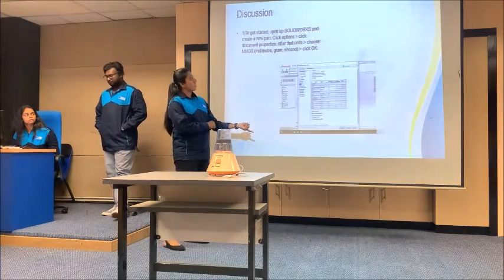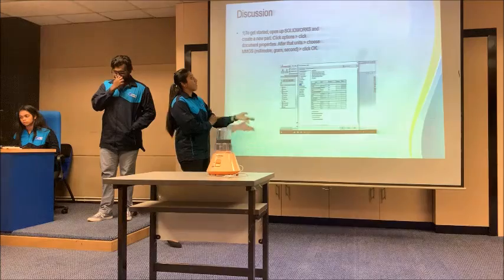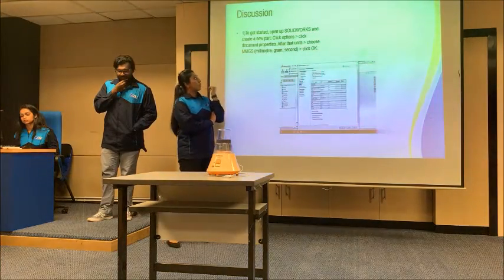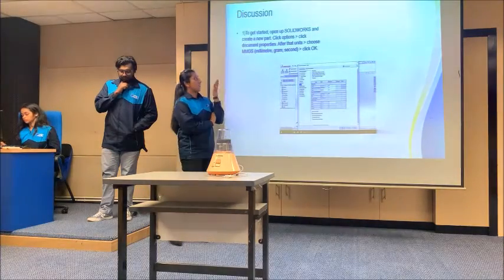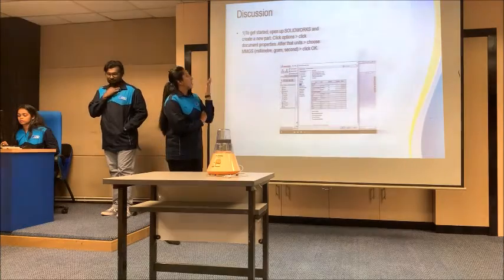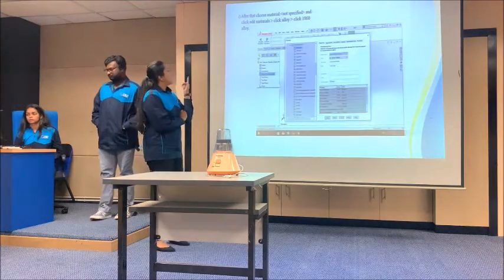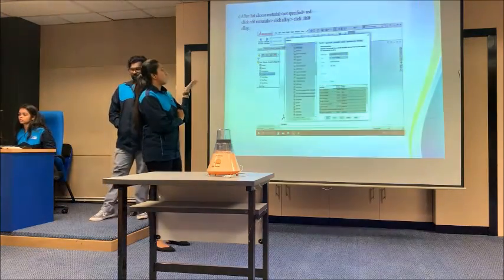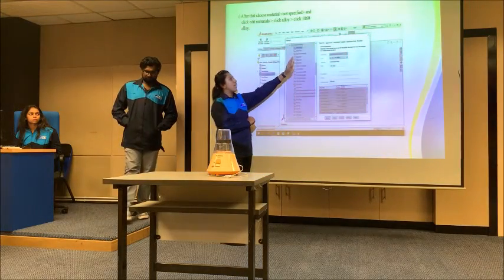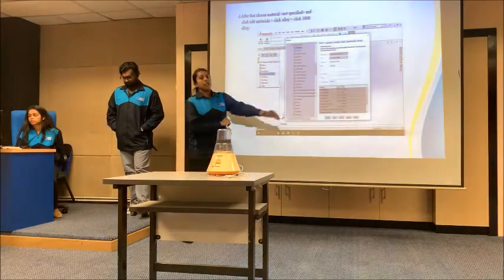Basically, using this software, we have to start by selecting the new part, then click the option and set our document properties. For mass units, we set it in mm. After that, we choose the material and which type of material. For example, we have attached a print screen where we selected 1060 alloy.